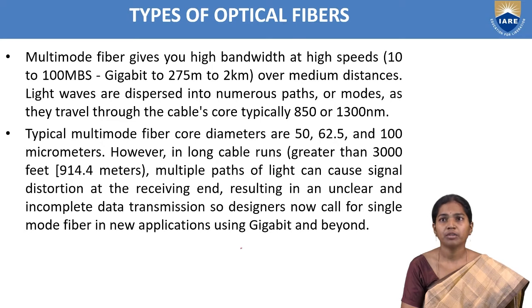So here, on long cable runs, multiple paths of light can cause signal distortion at the receiving end, resulting in an unclear and incomplete data transmission. So designers now call for single mode fiber in new applications using gigabit and beyond.